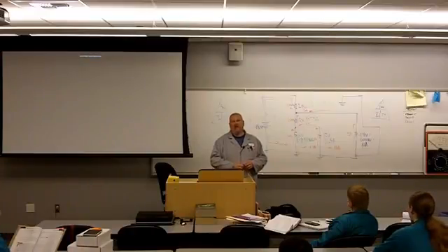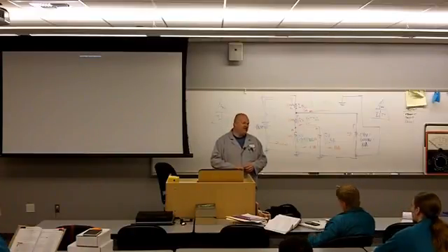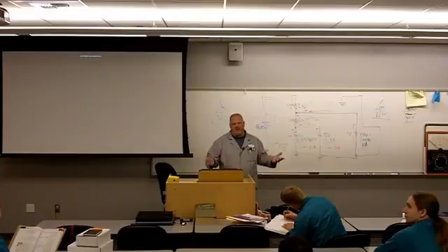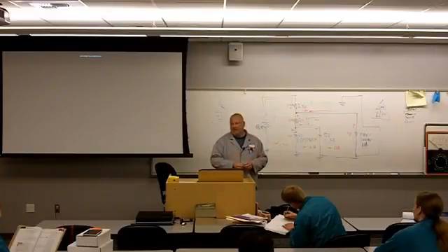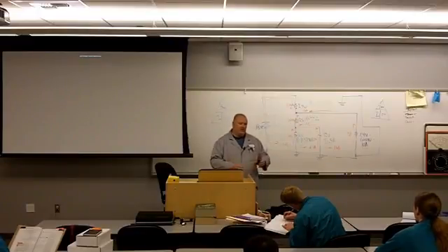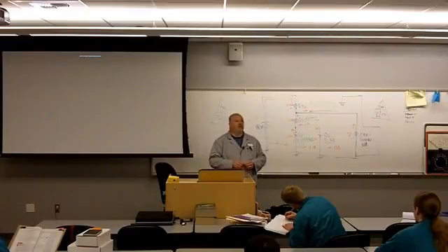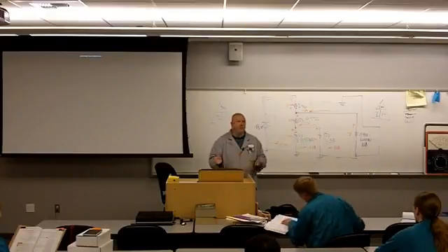So in the future, use that 1/10. If I use that 1/10, you won't get the answer that the author gets in the book. I don't know what you got to do wrong to get the number that the author gets in the book. So in the future, when you see loaded voltage dividers, use that 1/10 rule, unless you're told otherwise. You know, there might be an engineer that knows a lot more math than we know. They say, no, we want you to assume 15% or 20% or whatever. But you need some guidance.